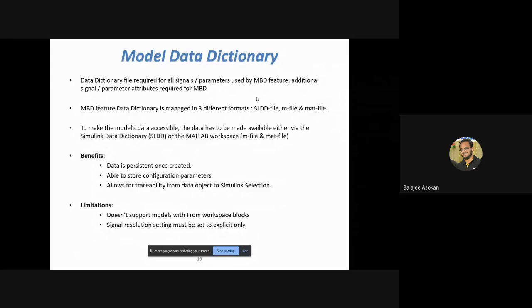Here it is much easier: I create it in my Simulink data dictionary at the click of a button, define the values manually, save it and close it. Once I save and close it, my MATLAB and Simulink model will not refer back to the workspace.